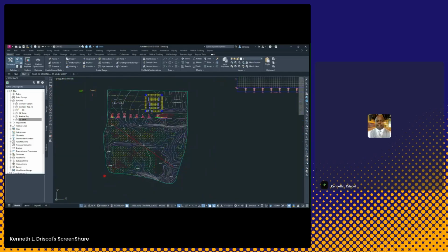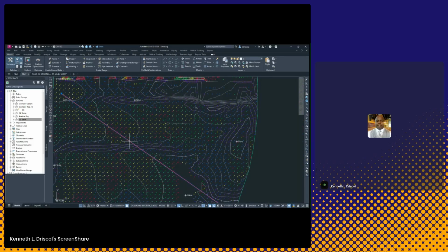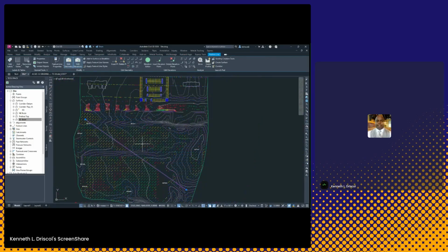So I'm going to select OK. So from this, if I pick on this, this is why I talk about using feature lines. If I come to this elevation editor, this tells me right now, this thing is over 900 feet. It has stationing, it has elevation, it has length, and then it has grades ahead and back. Now this little icon right here makes reference to it crossing a feature line.